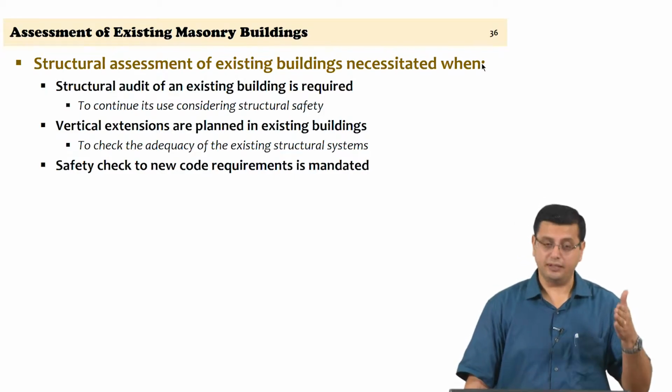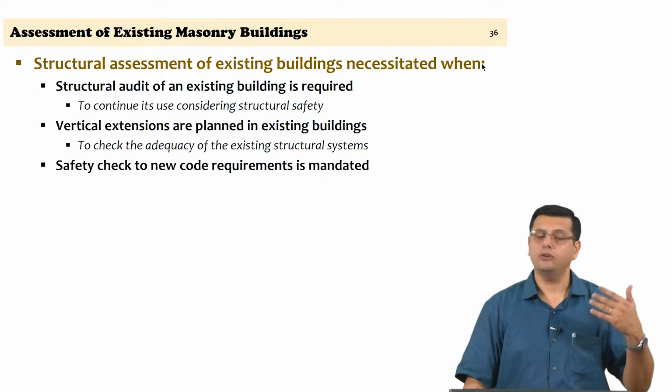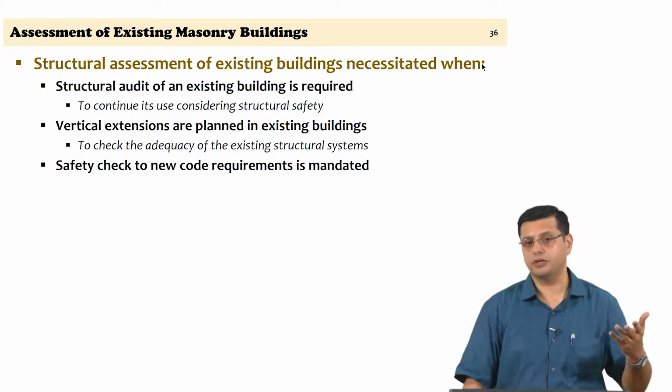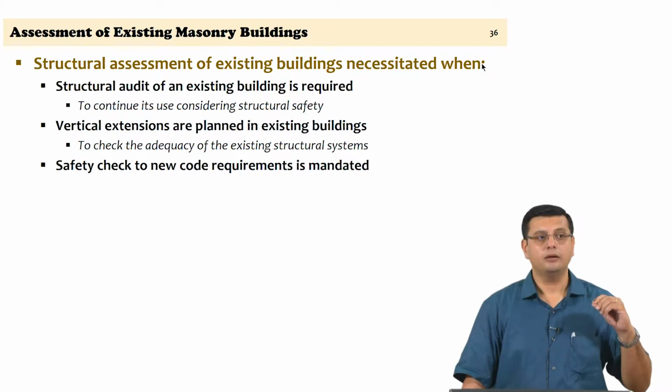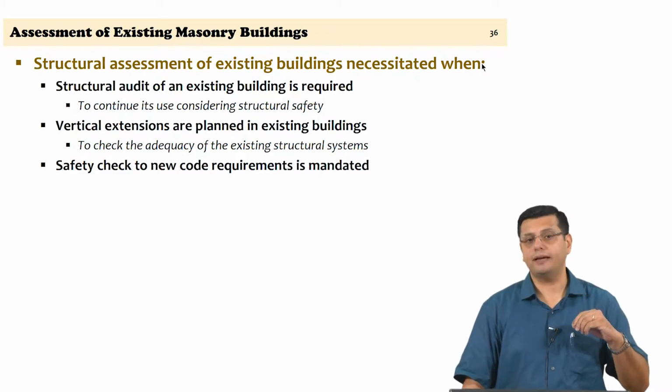As per the original code requirement pre 2002, for zone 2 you do not have to do a seismic design, but for zone 3 seismic design is mandatory.